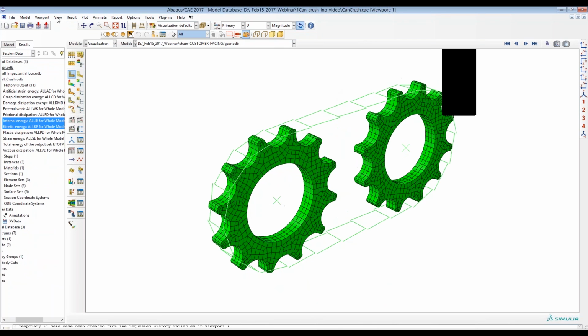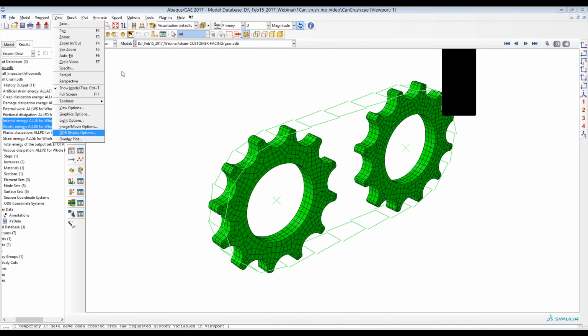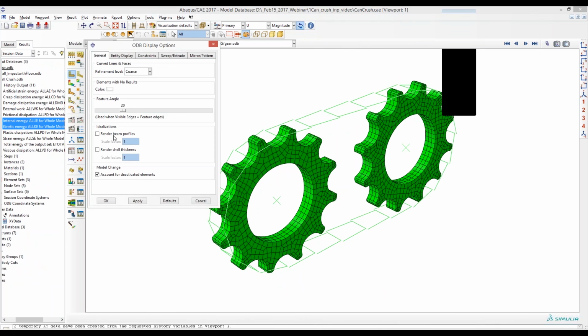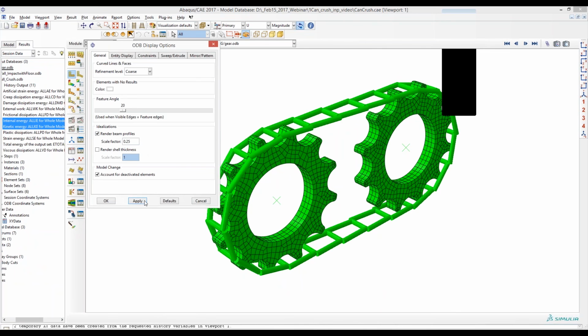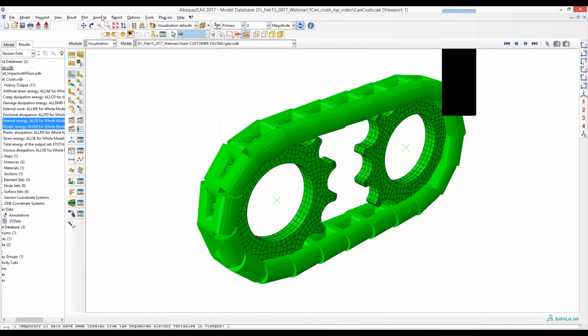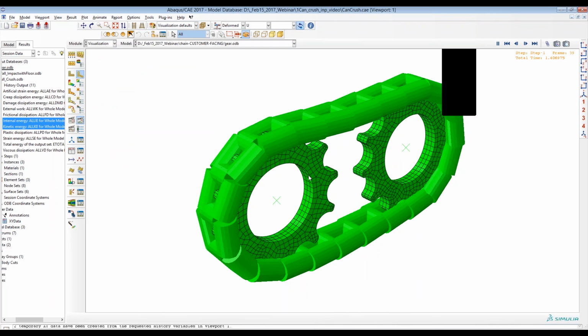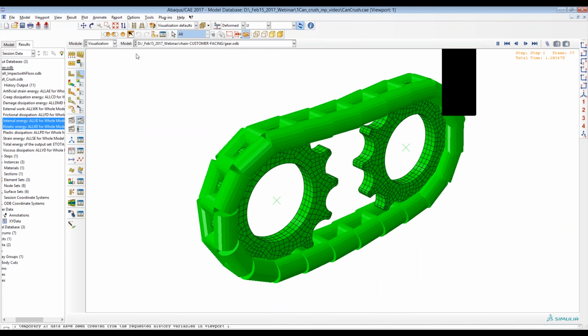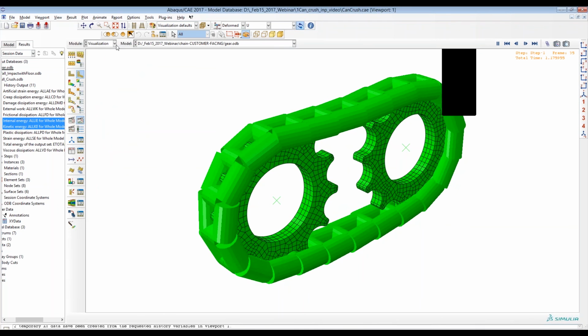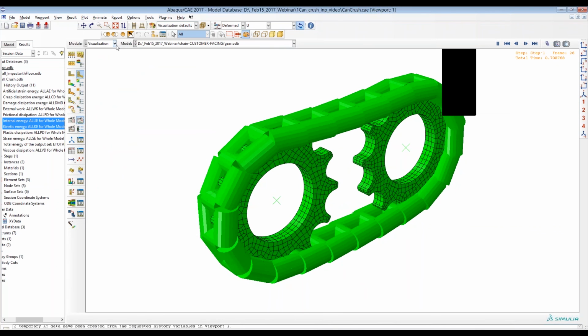So this one is a contact analysis where the first gear drives the chain, and by association the second gear. And so a very similar setup. We use general contact here, and we put these beam elements in contact with the chain. Nice thing about this is it's a pretty light-on setup for what can be a very complicated problem.